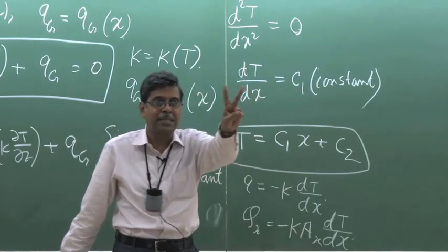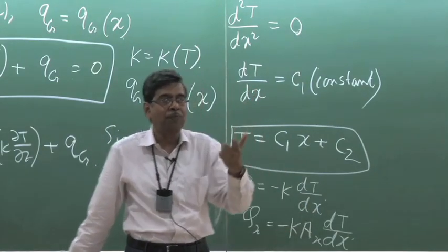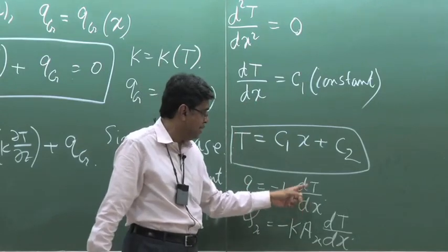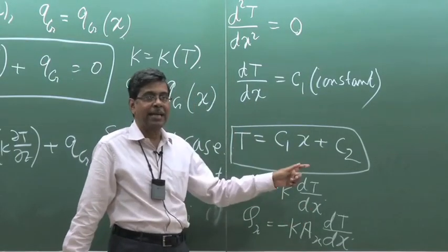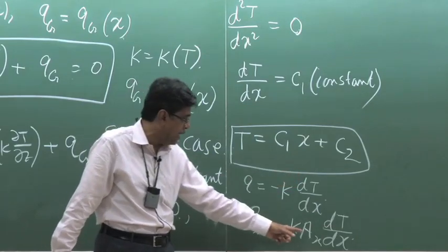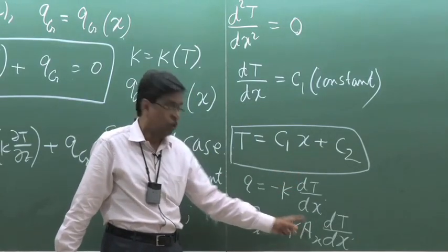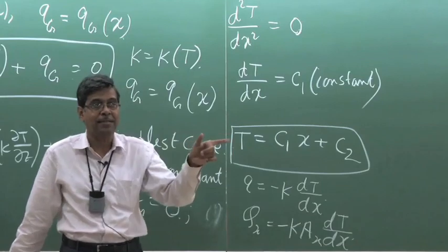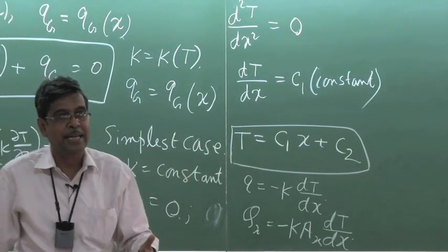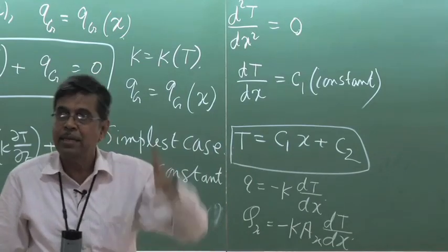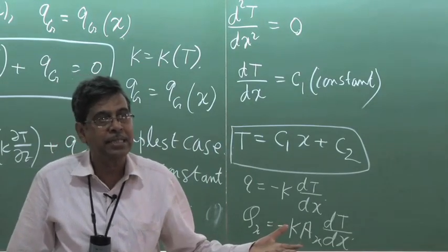If these two pieces of information are there, I will find from common sense that since dT/dx is the temperature gradient, heat is flowing along the x direction. So, therefore, no area is multiplied here to find the total heat flux or the total rate of heat transfer across an area A, which is nothing but the area normal to the x direction.